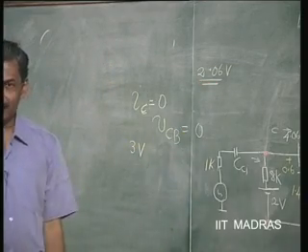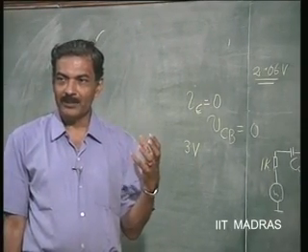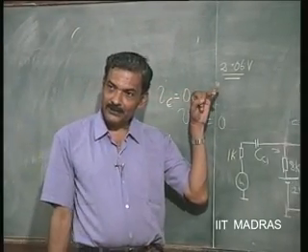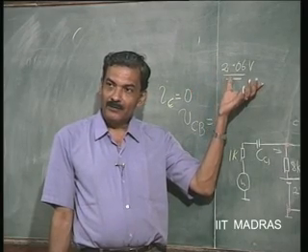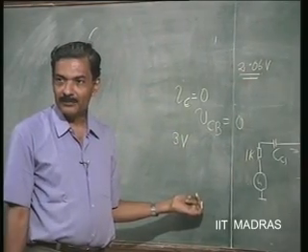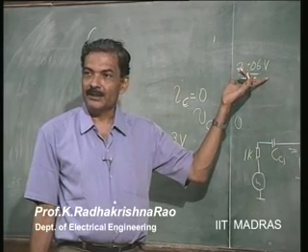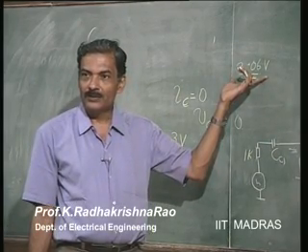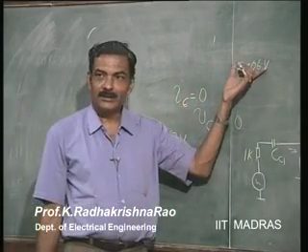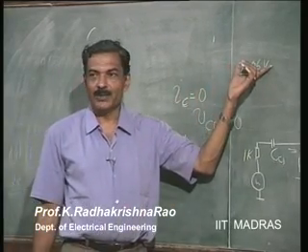It is asymmetric. This is not a design problem where you have been asked to design the operating point such that it is a symmetric swing. What it means is the amplifier goes to what? Saturation region. The transistor goes to saturation before it goes to cutoff. If you apply a sine wave, the first distortion that will appear in this case is due to what? Saturation. So, this is important. This will not occur. It is this that is important.